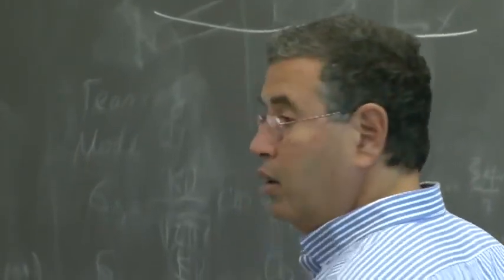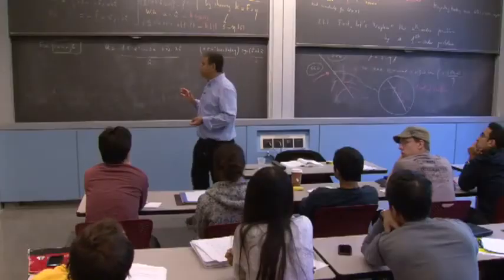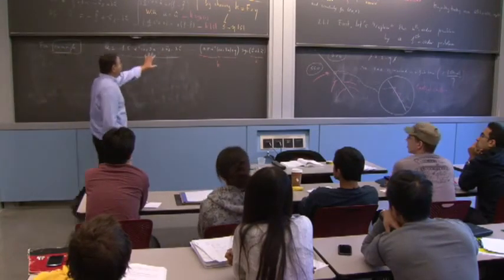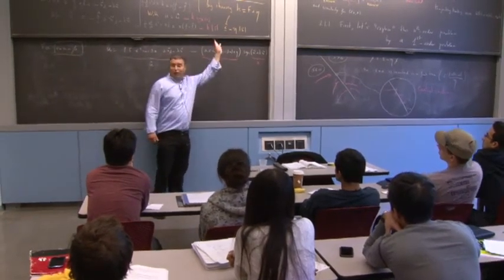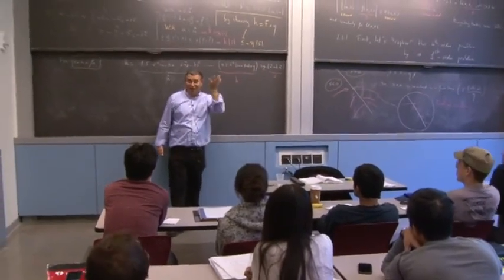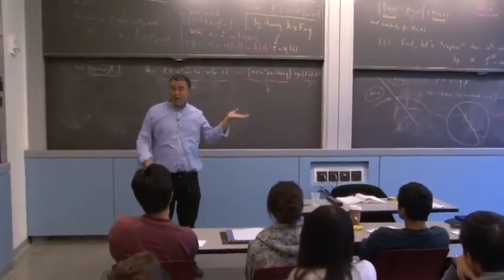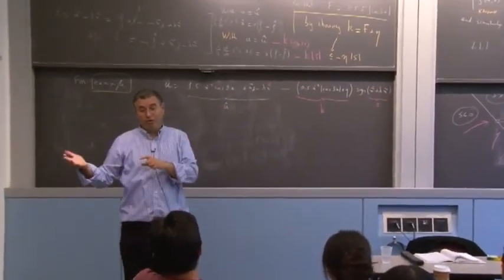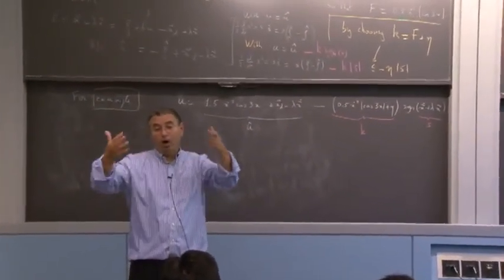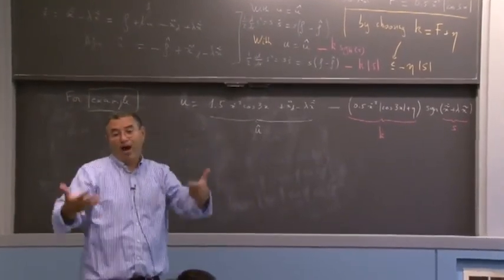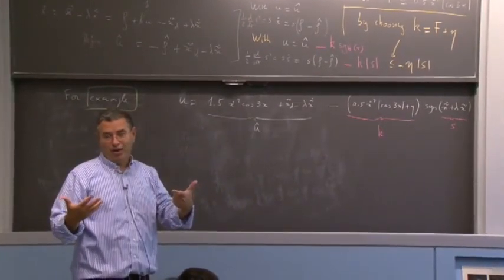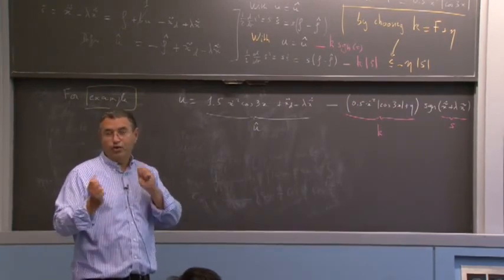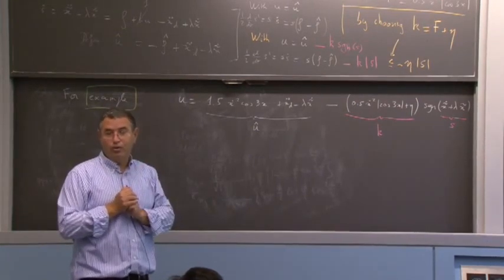Is it kind of sensitive to modeling errors, because the U depends on your original second order model? Yes. So how robust is it to modeling errors? So the question is which modeling errors, right? This is a very good question. So these modeling errors, it is very robust by construction. What I've just said about why we don't want in general chattering is that there's going to be other errors, namely unmodeled, presumably fast dynamics. Okay? And those are the ones which don't play well with chattering. Okay? And so that's where we're going to be able to play.